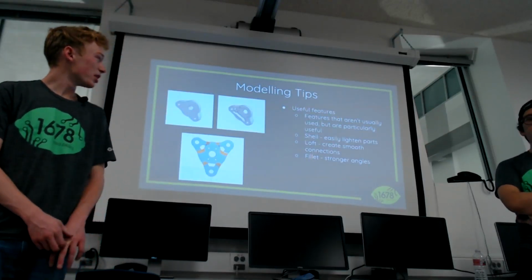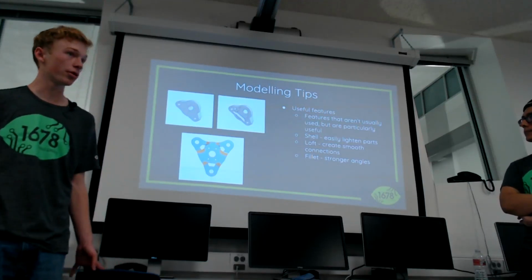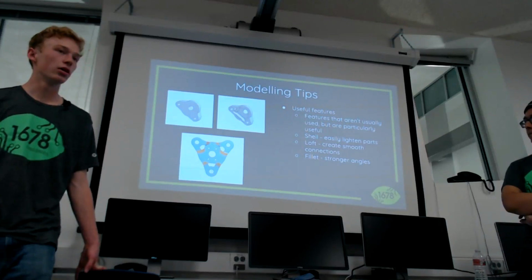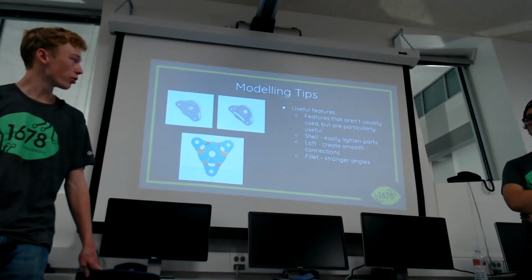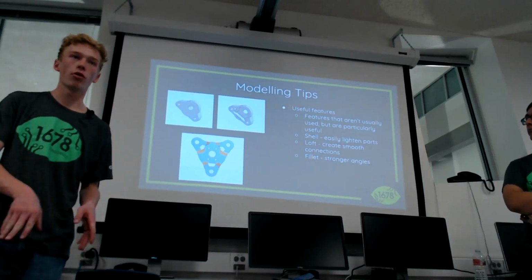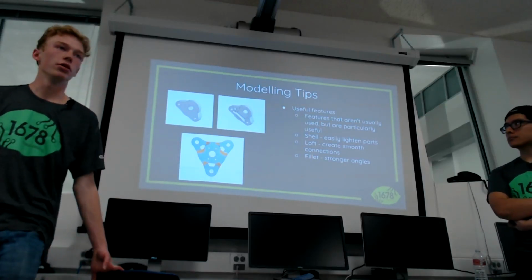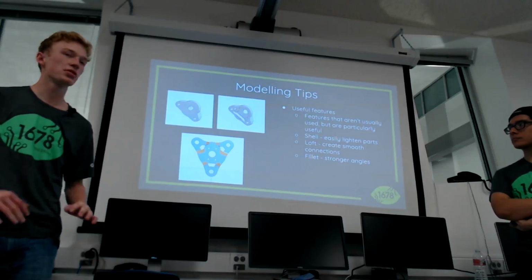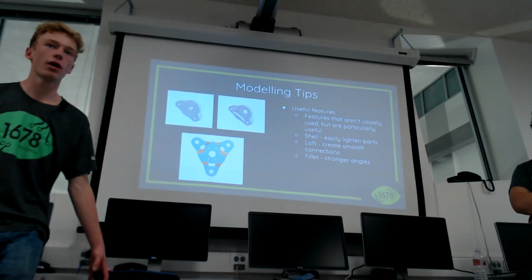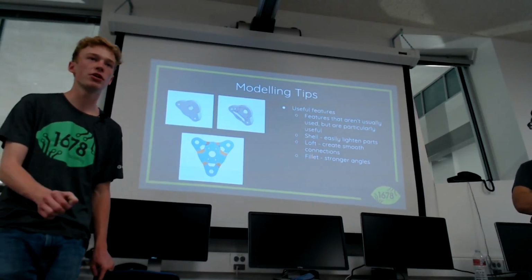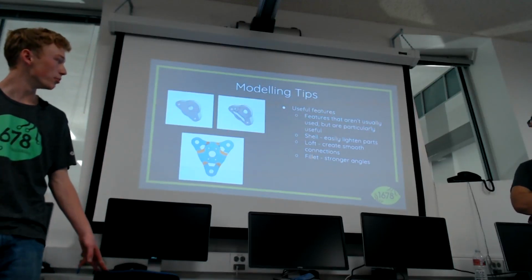And then this last slide about modeling is getting a little bit specific, so I don't want to spend too much time on it, but these are just cool tricks that can help with modeling 3D printed parts. The first is a shell. A shell is a super easy way to remove a lot of material in your parts. You can quickly model the part, knock out one face on it, and then remove all the material on the inside. It can make some pretty complicated cuts in a single feature. Most of the time, the most important material is the stuff around the outside anyway. The material on the inside isn't doing a whole lot. So when it comes to pocketing, rather than wasting time cutting out material, I'm in the habit of just shelling out the feature. It can really save a lot of material and a lot of time too.